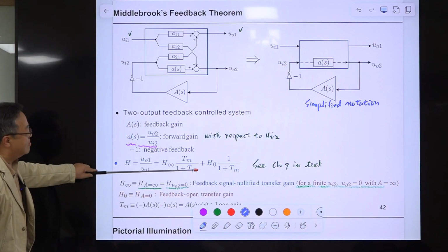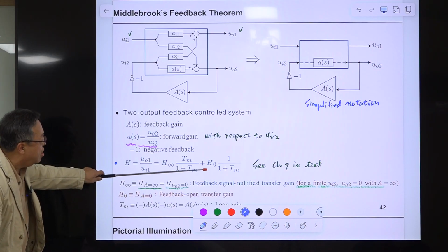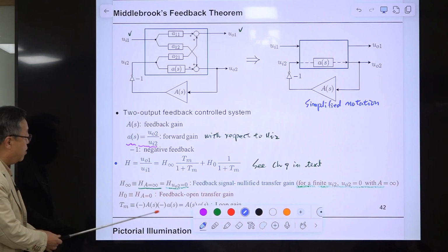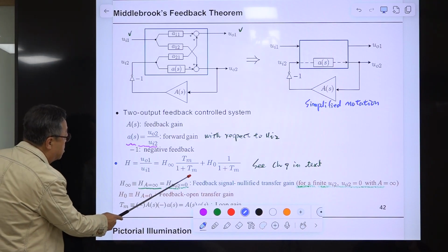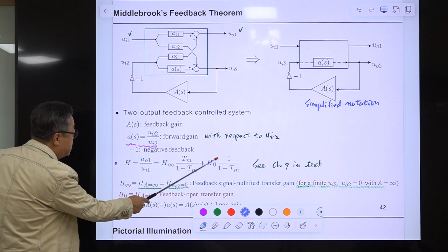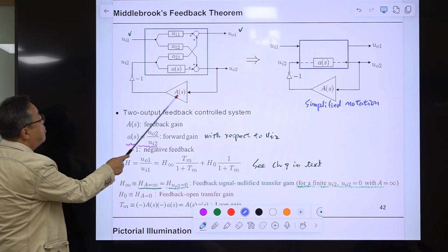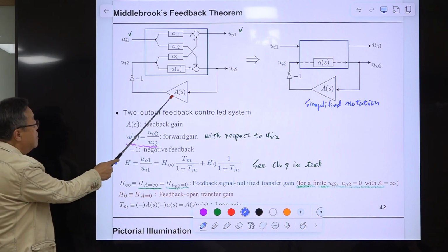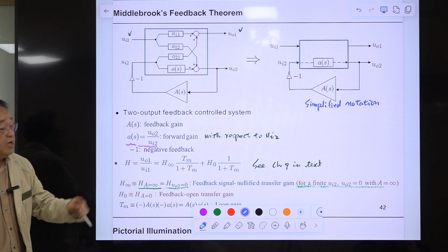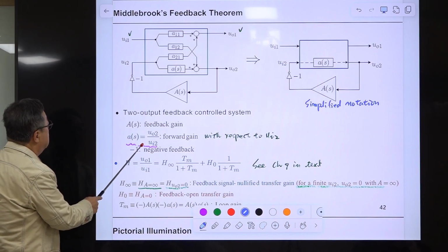So this is the equation. It looks complicated, but this one is much easier. This is 100% accurate. We have terms here. Tm is the loop gain, and we have H infinity and H0. And AS here is the feedback gain, maybe the voltage feedback compensation for our converter case. And this AS is this one.